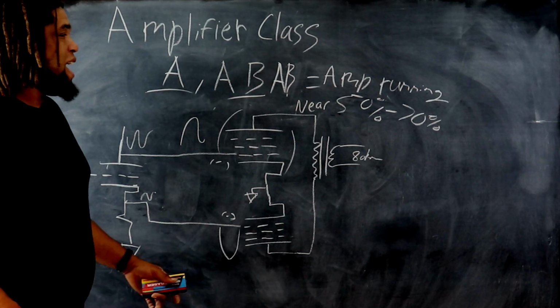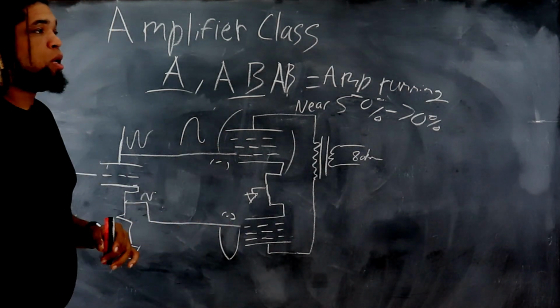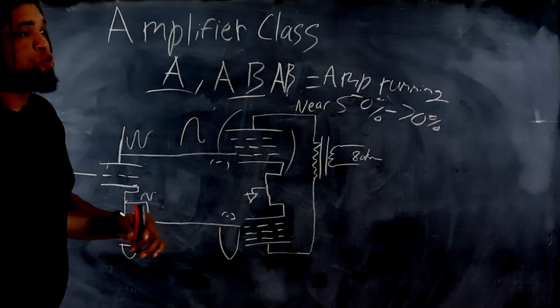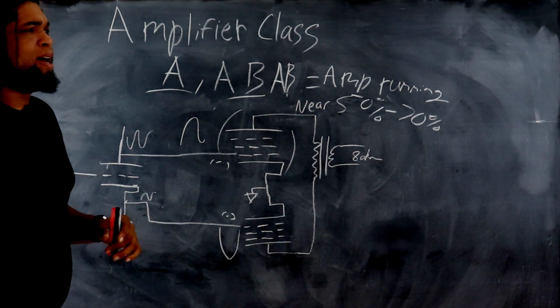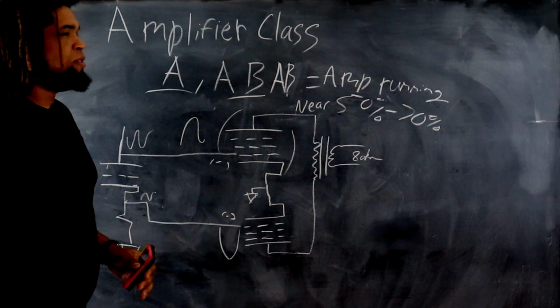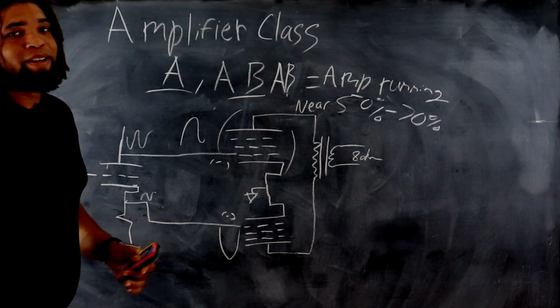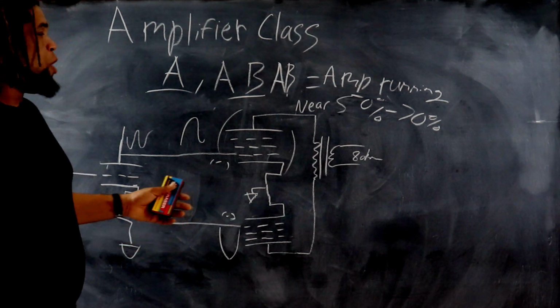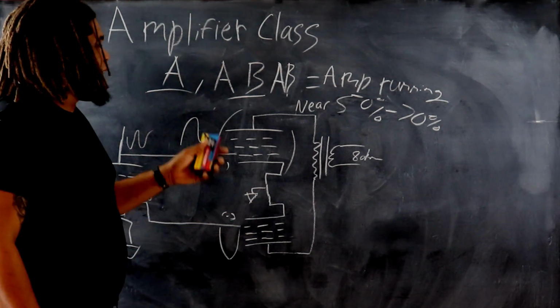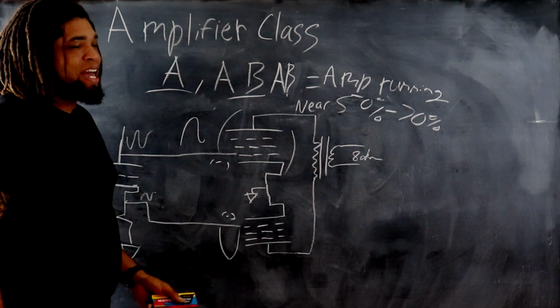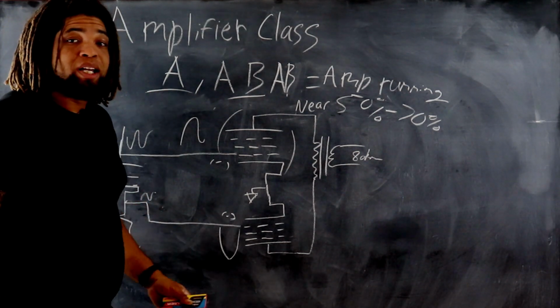Just as an aside, you can actually get more wattage out of Class AB2. So for instance, I believe if you have two pairs of EL34s in Class AB2, they could run about 75 watts. Whereas, let's say, if I just had one EL34 at Class A, I might be running 15 to 20, right?